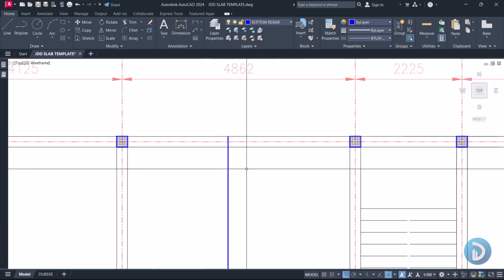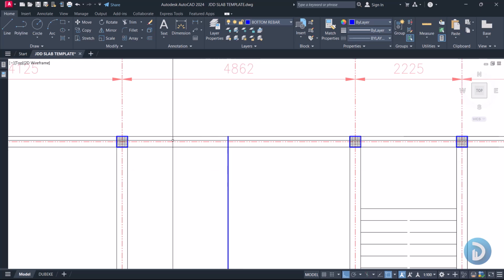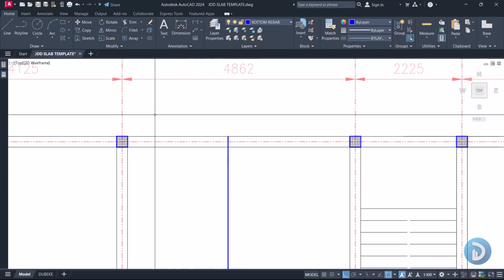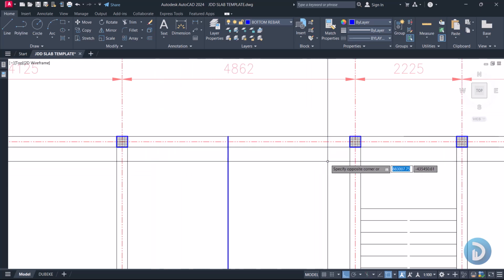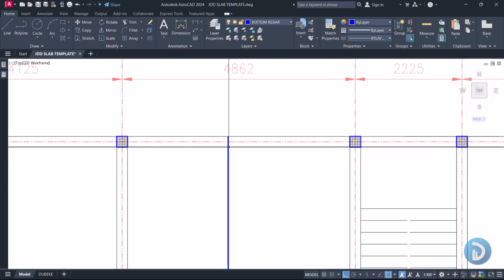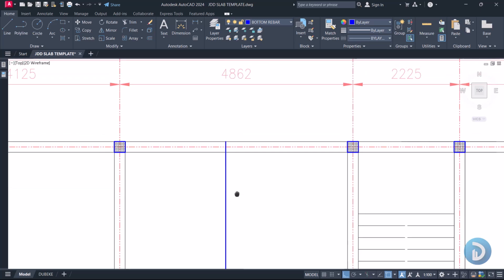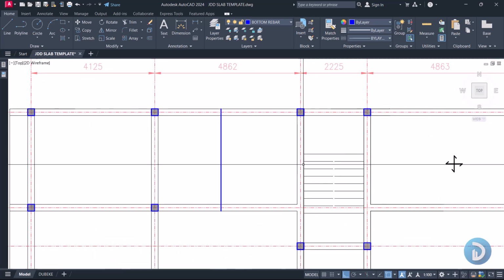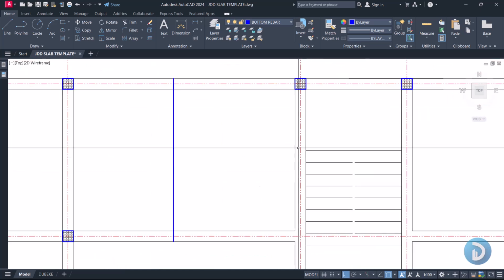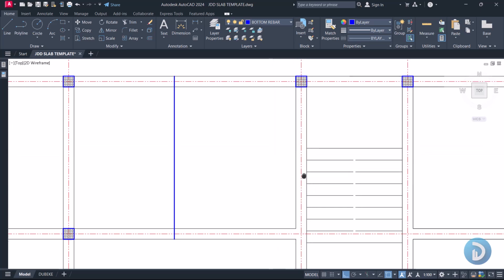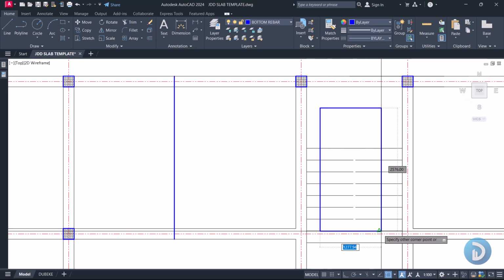So if you look at the topmost part of this reinforcement, you will agree with me that our slabs terminate at the end of this beam. Okay, so this beam is the final end of our slabs. So here we can have what we call a restrained end. If we go in the clockwise direction at the staircase as well, this is also a restrained end, because we do not have any slab coming at this part.